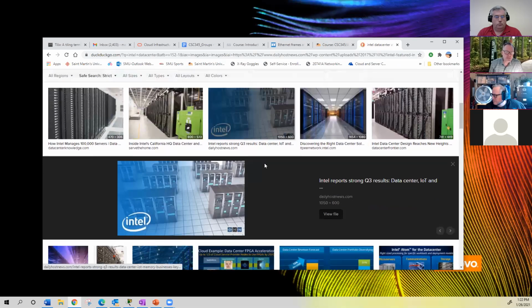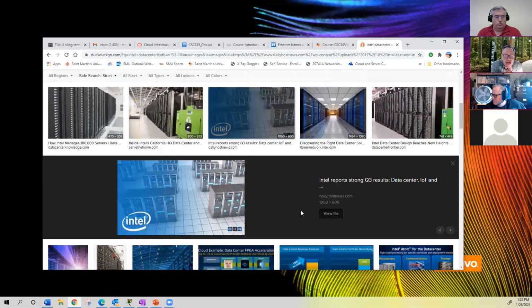Now here is an older design, and this is not a good design, okay? So you see how all the cabinets are dispersed throughout the data center. And in this case, it looks like no raised floor, although it may be a raised floor. It could be that the perforated tile is underneath the cabinet and it's blowing air up into the cabinet from underneath. So it's sitting on top of the perforated tiles, and then it's exhausted out into just the data center right there.